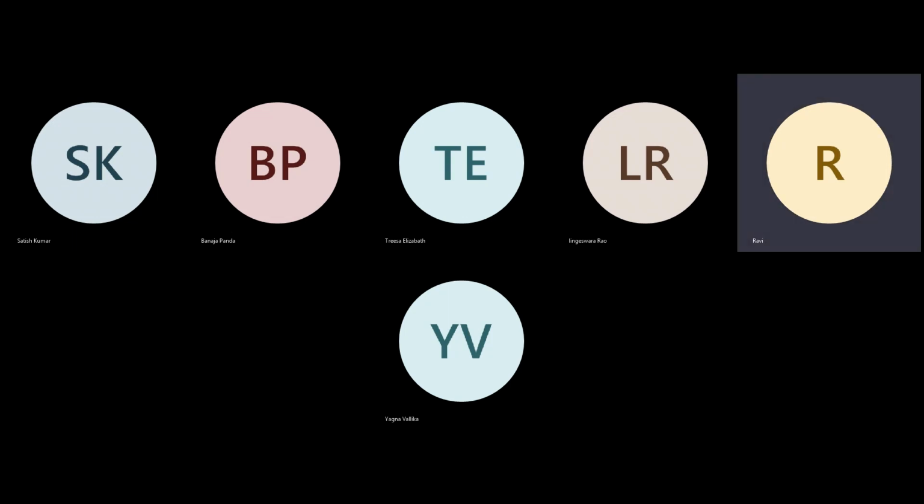So a tall set of cells is created to actually reduce area, and it will have only one clock pin. Internally, it will be connected like that. So register banks are used in a design to reduce the area. But register bank placement can have like 10, 12 banks, which means it will be like 10, 12 rows consumed.